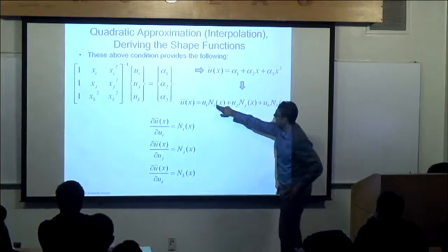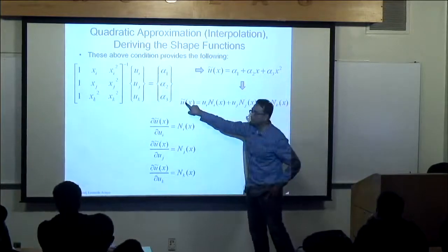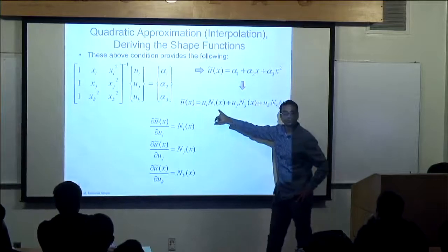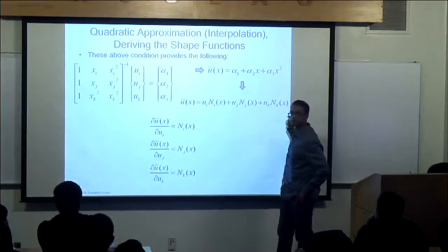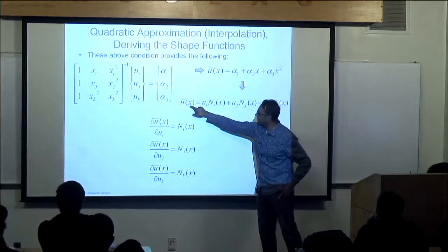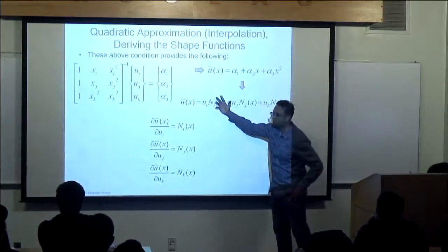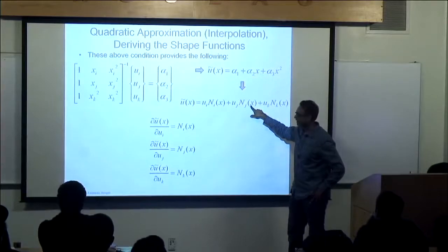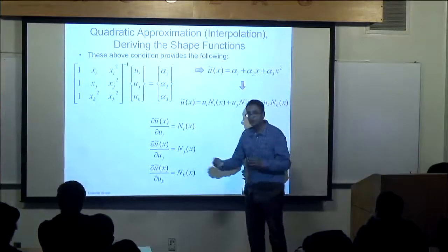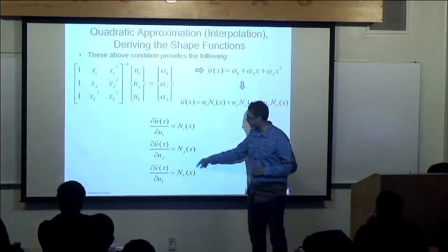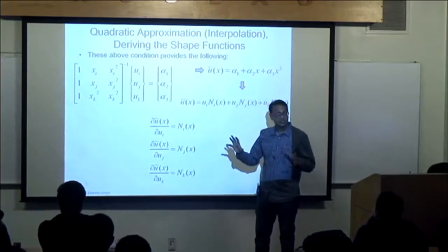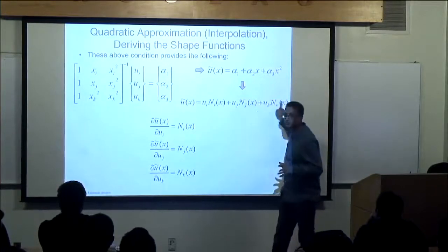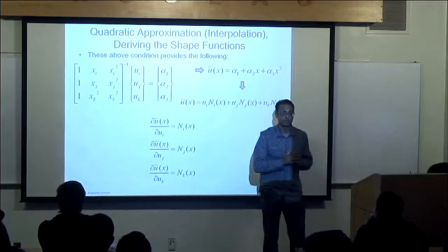And you can see it here, actually. Take the derivative of u tilde against ui. What do you get? Ni. I don't have to care about any of that. Take the derivative of u with respect to uj. What do you get? There's no uj here, it goes away. uj is there. I get Nj. Right? So I have a very quick way of getting these coefficients. And the basis functions. These are the basis functions which we've described as the shape functions.